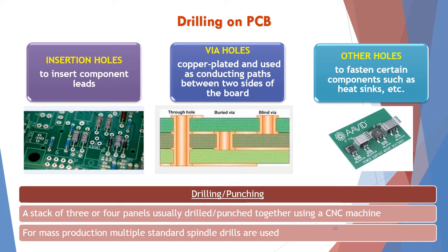Okay, so for non-high-tech PCB, you can stack different numbers of panels together before you drill them together. It can go up to like 150,000 holes per PCB board. Okay, so there are a lot. So that's why you can do the stacking and then perform the drilling process.